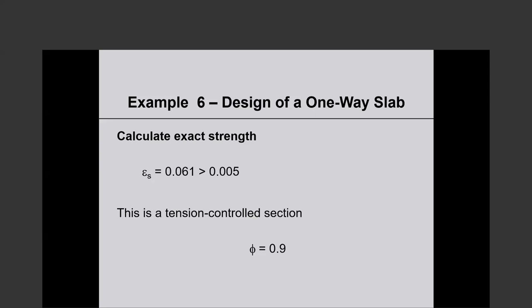I do not quite understand the thinking. If you have a slab integral with your beam, the slab is part of the beam. And the fact that the slab is part of the beam does not depend on whether you have some perceived deficiency or not.